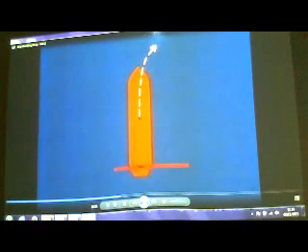Three component forces have been shown to act at the stern. 1. The helical flow striking the rudder, tending to turn the ship to port. 2. The upward flow into the propeller disc, tending to turn the ship to port. And 3. The variation in flow velocity into the propeller disc, tending to turn the ship to starboard. The net resultant of these forces is commonly known as transverse thrust. For most single-screw ships, it causes a gentle turn to port.